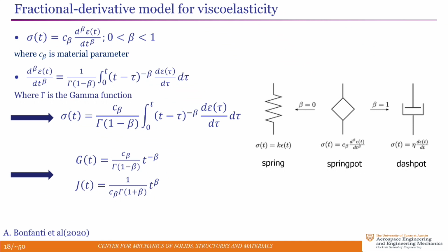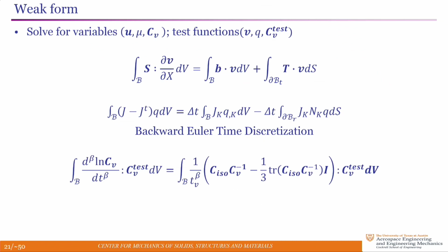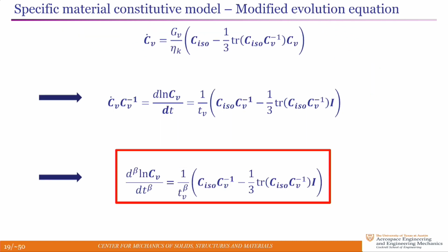This is something I'm going to skip. The viscous model is based on a fractional derivative, and it's just too dense to go through this early in the morning. But it's basically something that says that the power law of viscosity that we found for the creep process is going to be represented in the finite stretch domain by a fractional derivative model, where the fractional derivative of the viscous branch of the stretch tensor is going to be given by this part with a time constant, viscous time constant tau, to be calibrated. The term beta is also to be calibrated to give you the right power law of viscous creep response.